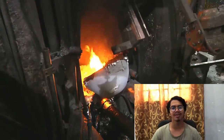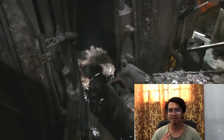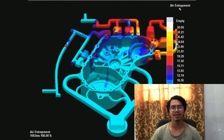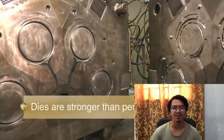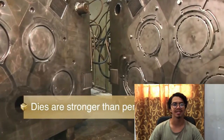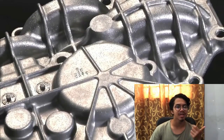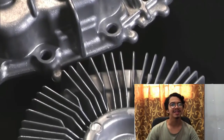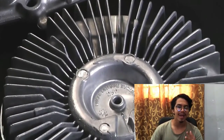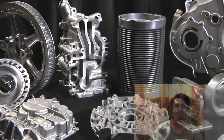by forcing molten metal under high pressure into a mold cavity. The mold cavity is created using two hardened tool steel dies which have been machined into shape and work similarly to injection mold during the process. Most die casting are made from non-ferrous metals, specifically zinc, copper, aluminium, magnesium, lead and tin-based alloy. Depending on the type of metal being cast, a hot or cold chamber machine is used.